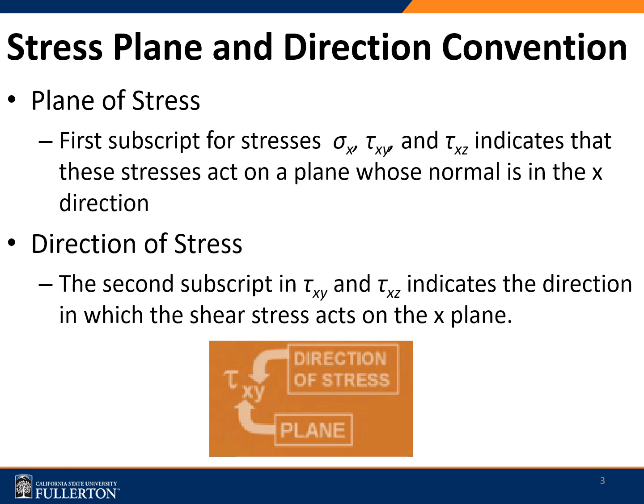And when we consider the stresses, for the subscript tau xy, the x would be the plane and the y would be the direction. The first subscript is the plane, and the second subscript would be the direction of the stress. In case of the sigma sub x, there are two x's, the sigma sub xx, but we simply denote it by sigma x.